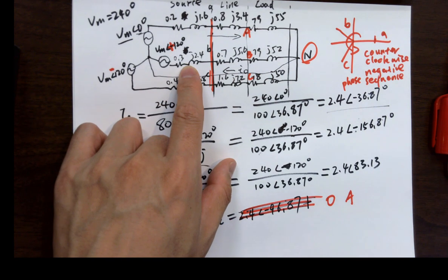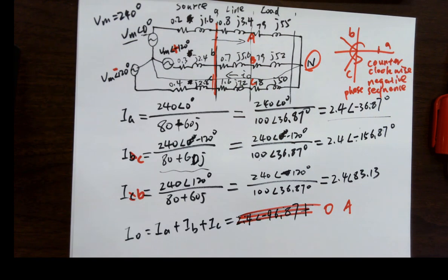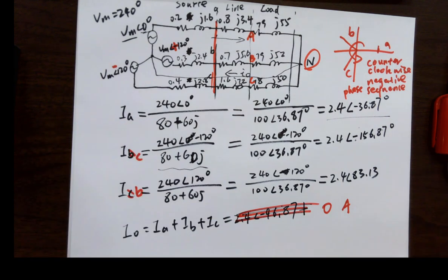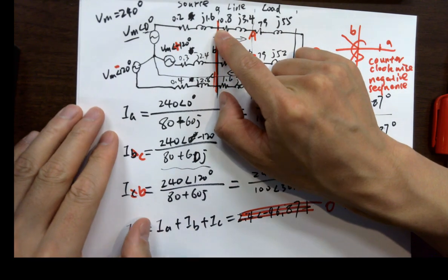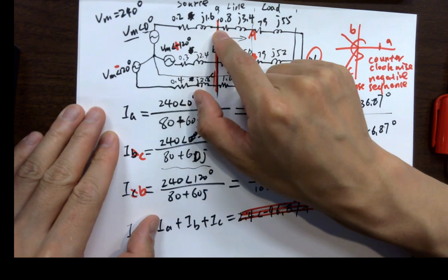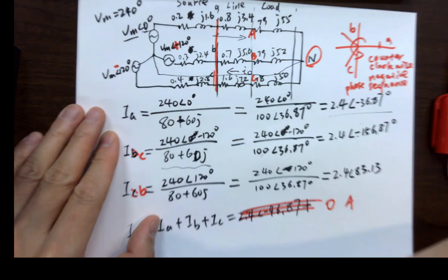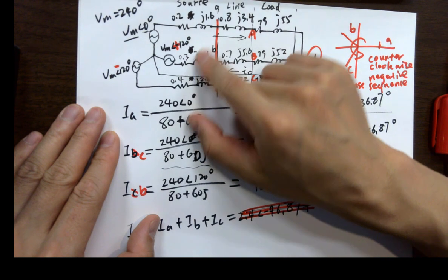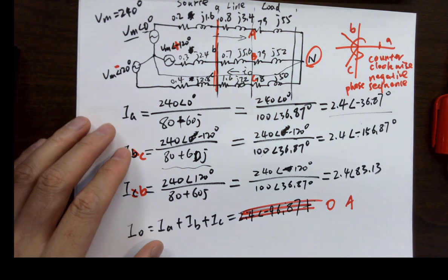and if we divide it by this phase, let's calculate and see what we're getting here. That will be a lot of calculations, and there is a better way to do it. We need to find out the voltage here, so we use the voltage here minus the voltage drop and see what the voltage is here. We just need to verify probably two of them, to see if they are 120 degrees apart from each other, okay?